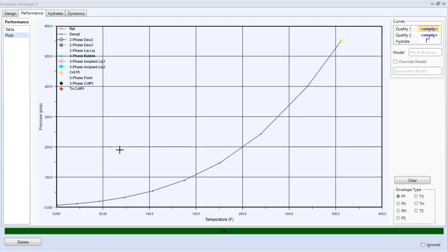Here on my screen, you can see a pressure-temperature chart of n-butane, and the blue line represents the equilibrium phase between the liquid and the gas. On this side, I have low temperature and I can have high pressure, and the gas phase or the vapor phase, where I have high temperature and I can have low pressure.